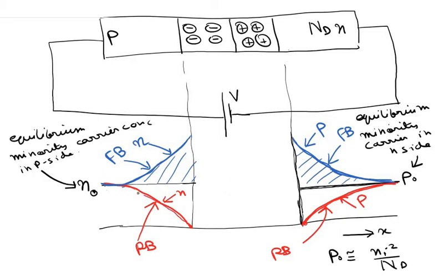So as the diode gradually moves from the zero bias condition to the reverse bias condition, the minority carrier concentration, proportional to the area under this curve, should actually be removed. That is to say, as the diode gradually moves from forward bias to zero bias and then to reverse bias, the total accumulated excess minority carrier concentration just outside the depletion region must change before the diode can actually switch its behavior.